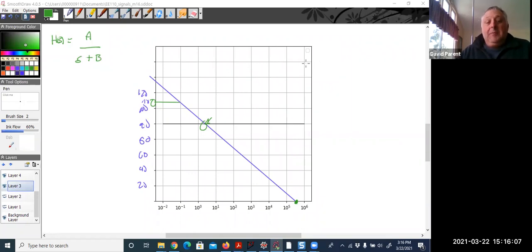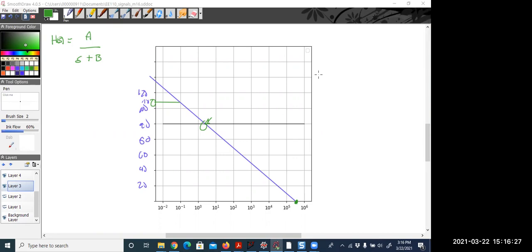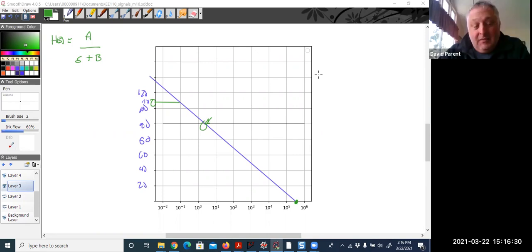Should you use the minimum values from the data sheet? Yeah, if you want it to work every time, but there could be times where you might be allowed to use the typical values, and LTspice will use the typical values, actually. You probably want to use the minimum values, because I was doing a pulse width modulated DAC and trying to make the highest frequency one, and it wasn't working.